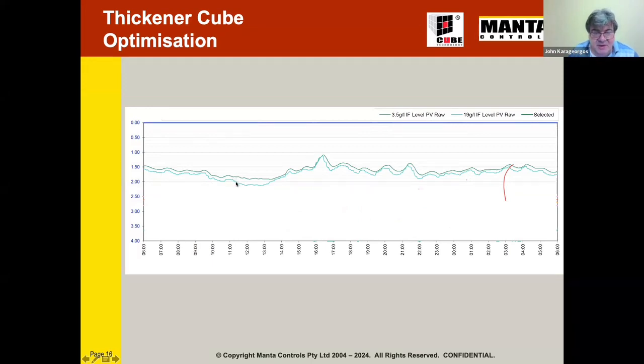So the relationship between these interfaces, if I had all 5 running, whatever they may be: when particles are settling really well, they're close together. When particles are not settling really well, they become separated. So you can use that information to then use flocculant to manage how these interfaces separate.